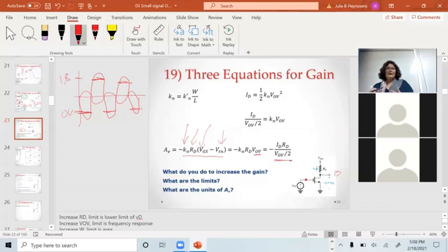If I make this gain so big that the output becomes bigger than my power supply range, I get this clipping. And unfortunately, engineers refer to that as saturation. You get saturation when the transistor comes out of saturation, because it basically shuts everything down.